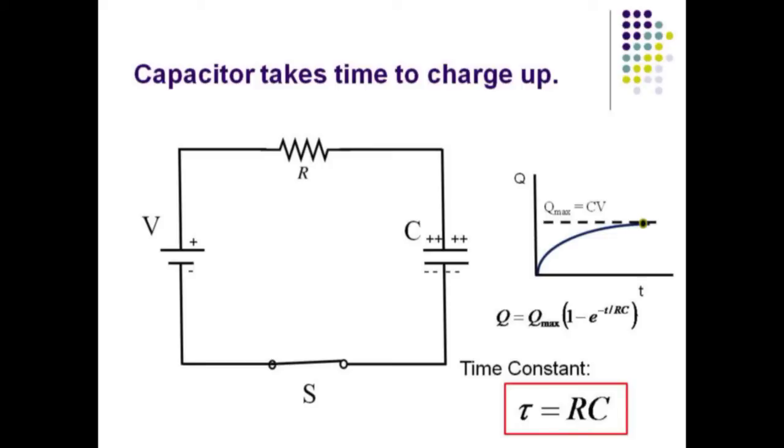the natural logarithm. Although in theory the capacitor never fully charges, in practice it is about 2/3 charged after one time constant given by the product of R and C. A large value of resistance will slow the rate of growth, and a large capacitor will take a long time to charge.